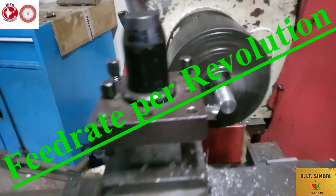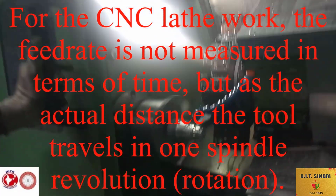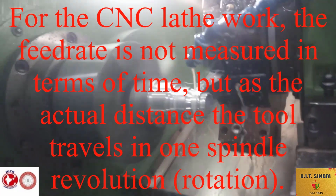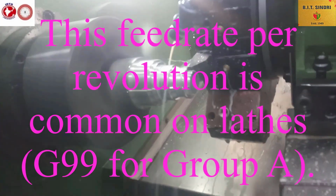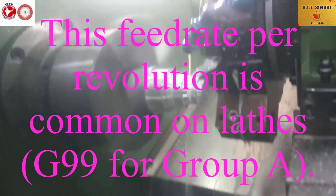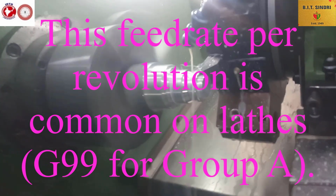There is a significant difference in G code used for machining center and lathe. For CNC lathe work, the feed rate is not measured in terms of time, but as the actual distance the tool travels in one spindle revolution, that is, rotation. This feed rate per revolution is common on lathe, G99 for group A. Its value is modal and another feed rate function cancels it, usually G98.